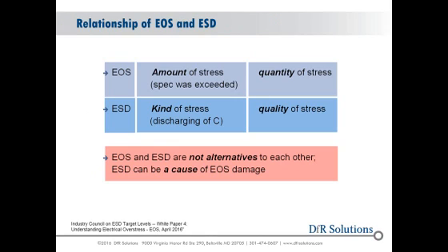Jeff? Yeah, so this is a chart from the release about a week ago of white paper 4 from the Industry Council. That is 189 pages about EOS causes, effects, and industry analyses all combined in one. And the big takeaway, the difference between EOS and ESD, is that ESD is almost entirely an electrostatic charge that is stored in a capacitance, whether it be the human body effective capacitance or some board or chip level parasitic capacitance between a reference plane.